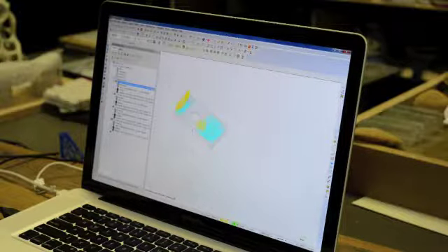Quick note that I just thought of a while ago but didn't say. One reason this is going so quickly is because we have very nice clean surfaces. If you work with meshes, you may have thousands of surfaces that you have to select in order to get your drive surfaces working. So keep your surfaces clean.